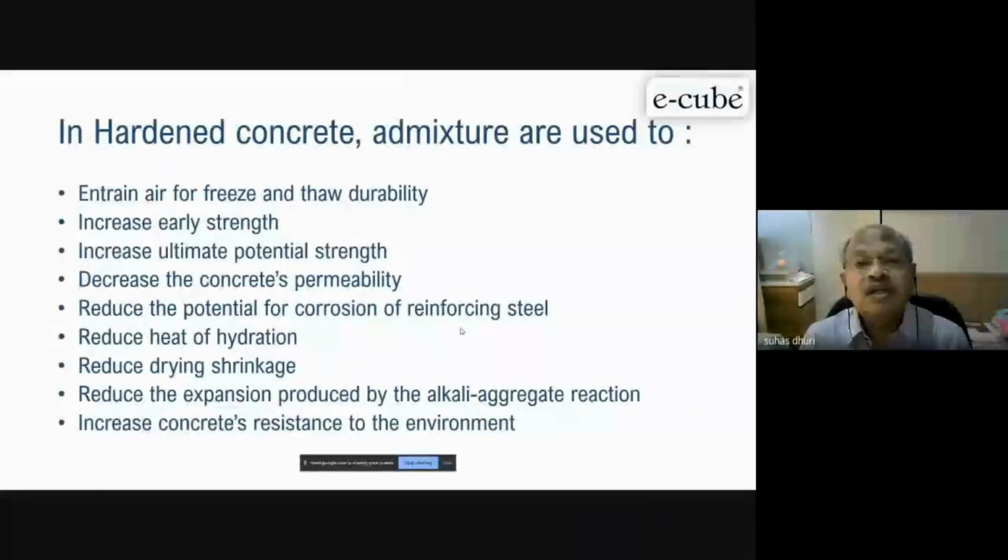We are using a lot of other supplementary cementitious materials, in combination. So once you use those materials, the hydration process starts even after 28 days. And generally also, concrete doesn't stop gaining strength year to year. We have studied up to 10 years even, it goes on increasing the strength. But the gaining percentage is low.